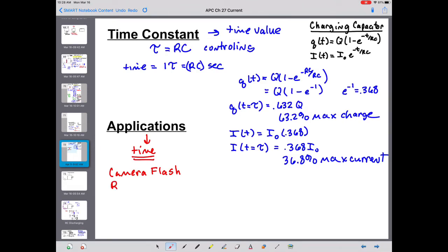By the same idea, RC circuits are used in pacemakers, because a pacemaker is something that's going to need to deliver a charge at a regular time. So you use an RC circuit to build up charge, and when it is at the appropriate voltage to deliver that shock across the heart, that voltage level trips a switch, which then completes a circuit and has the discharge. So RC circuits are used for a lot of things where you need something to occur at a regular period of time.